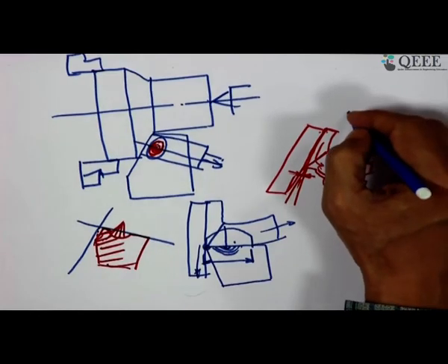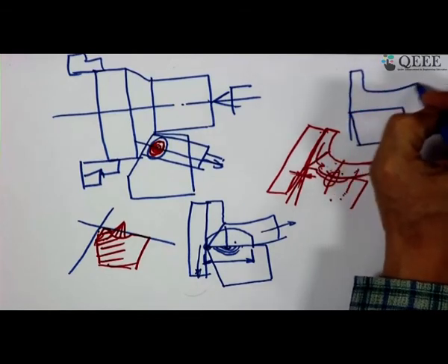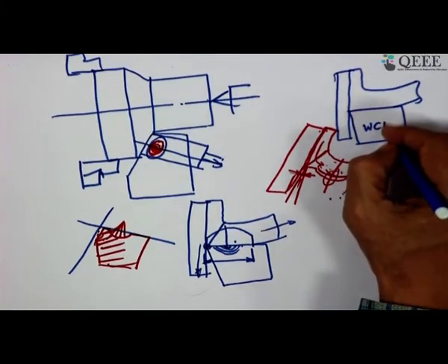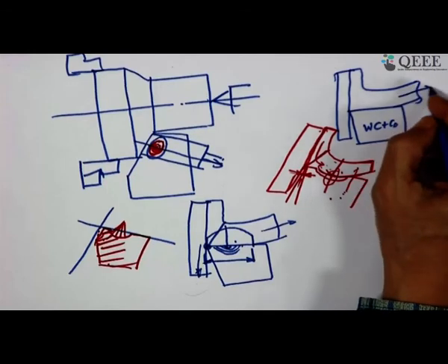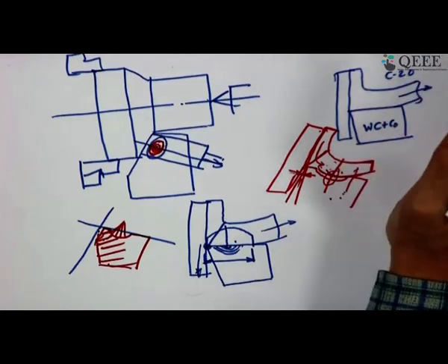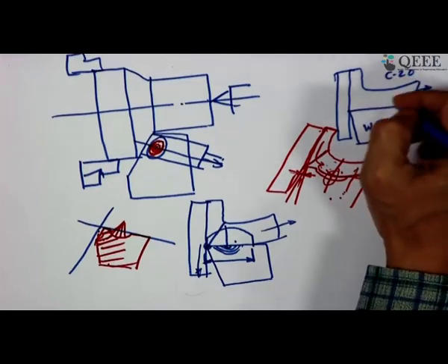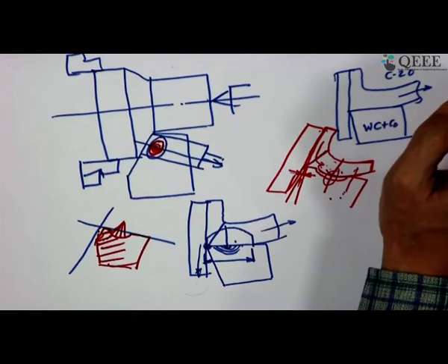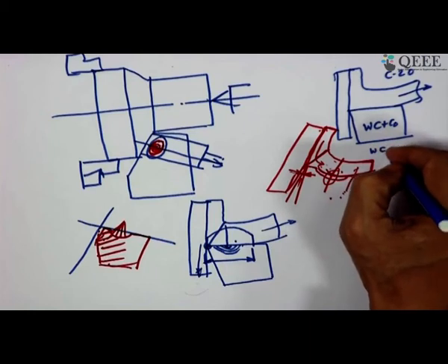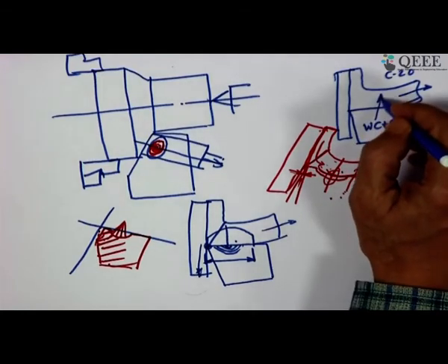Say I can give you a very specific example. This is the chip. Now, this is tungsten carbide plus cobalt, and this is your low carbon steel, say C20 steel, and you are machining with a speed which promotes such a thing. So, you can understand this is 0.2% carbon. What will happen at that temperature, if you take the whole thing to that temperature, is that it promotes dissociation of tungsten carbide to tungsten and carbon. It will dissociate. Then this carbon will migrate to this side.